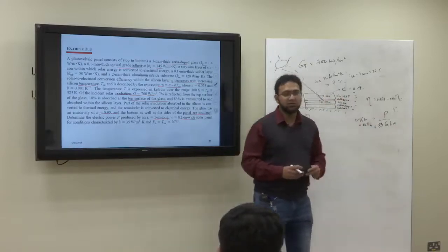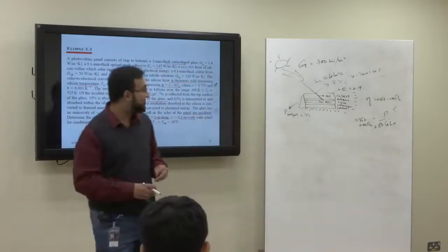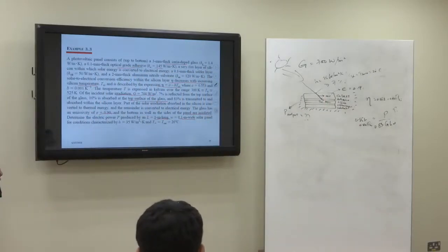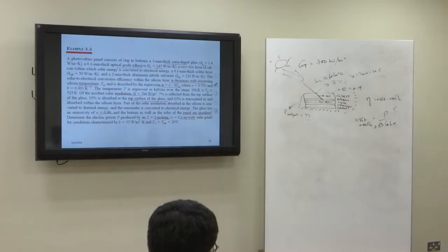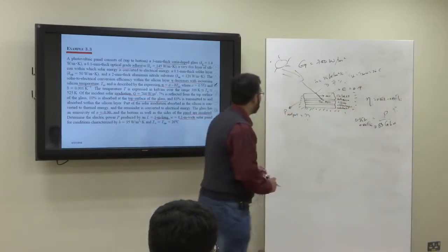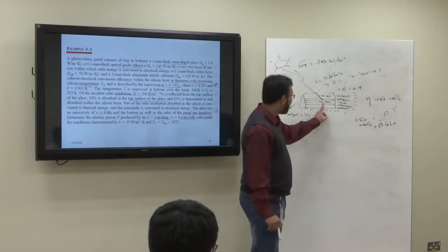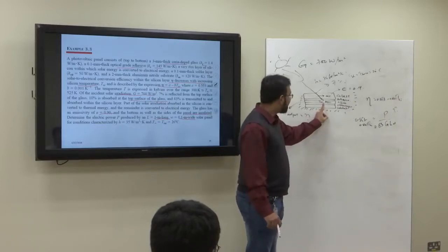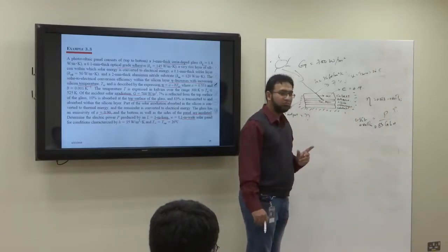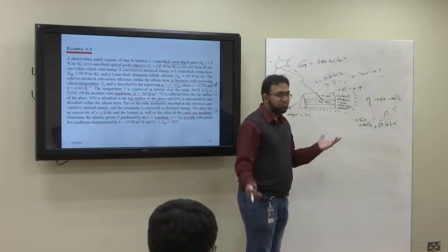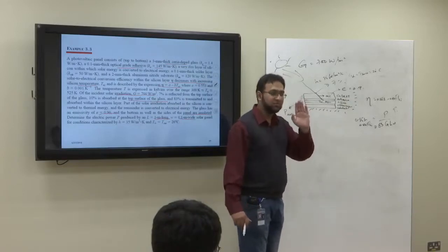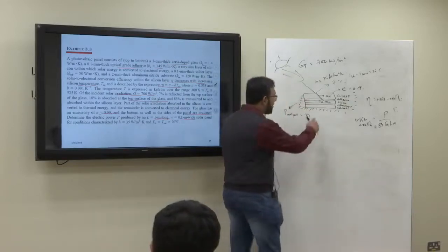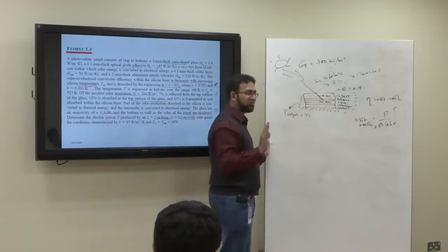P was required. Now, to find the temperature of the silicon chip, you have to enter into the heat transfer circuit. So let's make the heat transfer circuit. One thing is clear, that the heat is coming from the silicon. What are the directions where heat can go? Up. Even down is insulated. It cannot go down. Heat has to move up. So all the layers below the silicon chip are useless for us.